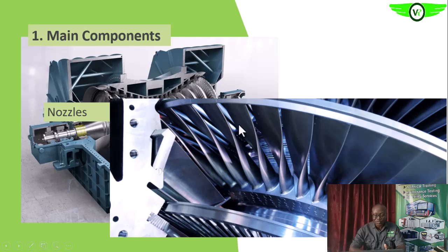So as the steam is going through, here is wider than the rear, as the steam is coming out. So that constriction helps to throttle the steam, thereby increasing its velocity. Remember, as it is coming out of this spacing, it is now re-exposed to a very wide, that is a larger volume in the turbine. So once it is exposed to that larger volume, what happens to the pressure? The pressure will drop.